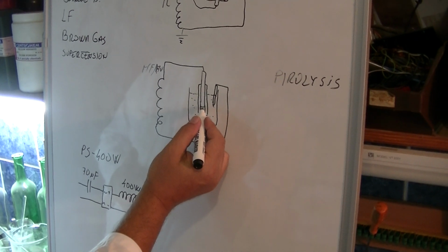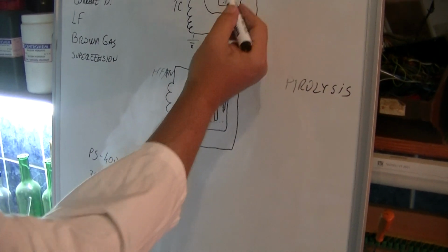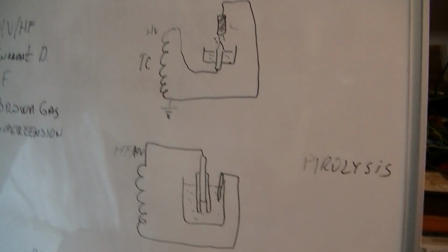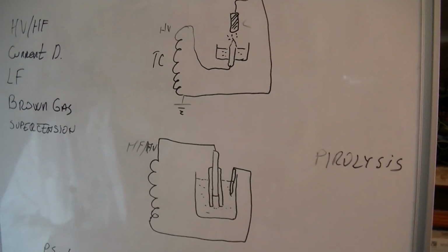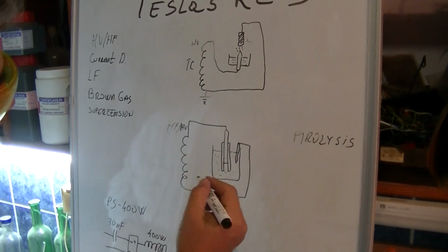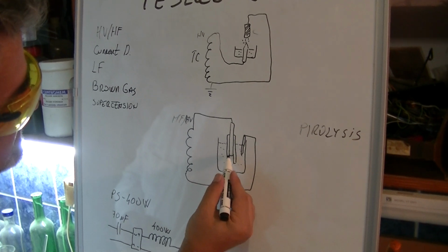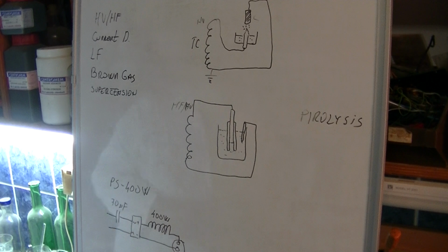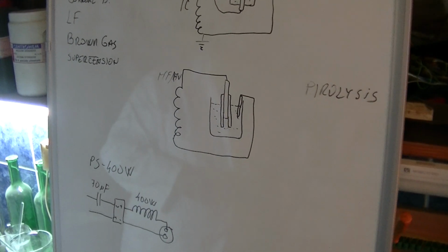When this surface is carbonized, it is going to be like carbon, and it starts to produce carbon dioxide and carbon monoxide. That is one aspect. Another is that it is conductive. It's not dielectric.